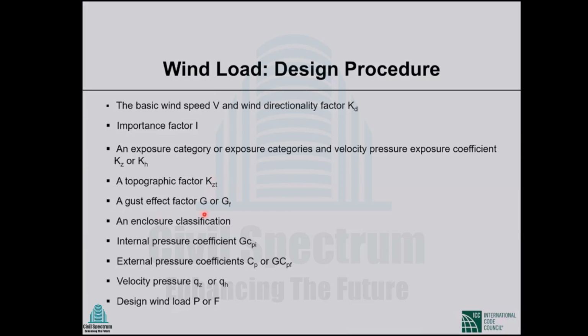Gust effect, it was there in the previous code. Now there are many diagrams, called figures in the code, from which you have to calculate and determine these factors. And enclosure classification is there, that is, whether it is completely enclosed, partially enclosed, or open type. Based on that, your calculation will be different.